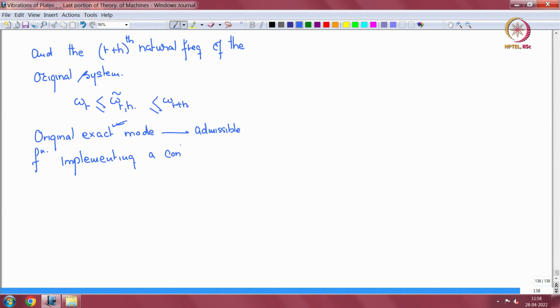Now, in terms of continuous functions you can't tell how many constraints this is equal to, but it is a constraint, and therefore what does it say? What it says is that the new natural frequency, let us say the first natural frequency omega tilde 1, the constraint is unknown, but it is greater than omega 1.